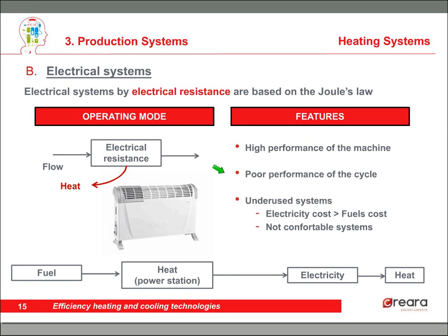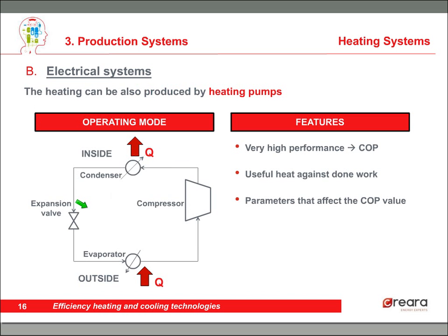Also, it is very important to understand that the electricity which this equipment needs to work is a lot more expensive than the equivalent in thermal energy. The electricity kilowatt hour costs about 3 times the fuel kilowatt hour. So not a good thing to have in our installations.